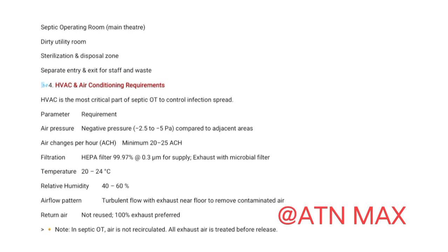Temperature, 20 to 24 degrees Celsius. Relative humidity, 40 to 60%. Airflow pattern, turbulent flow with exhaust near the floor to remove contaminated air. Return air is not reused; 100% exhaust is preferred. Note: in a septic OT, air is not recirculated. All exhaust air is treated before release.